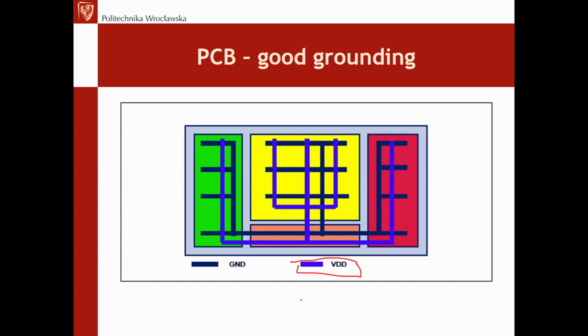have a parameter called power supply rejection ratio. So the circuits usually reject power supply changes, reducing them by many orders of magnitude, which means that any variations or noise coming on the VDD line are less influential than the choices on the ground. The ground is critical. Remember, the ground has the highest priority on a PCB.